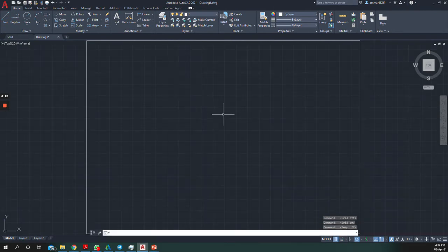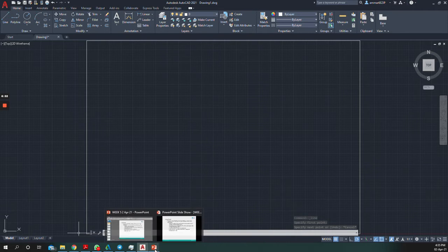If you click on F9, you can snap like this, snap off. If you click on F9 again, snap on. If you choose line, for example, no snapping there. So F9, snap off, line. Okay, you can do the snap off and grid off by choosing the line.